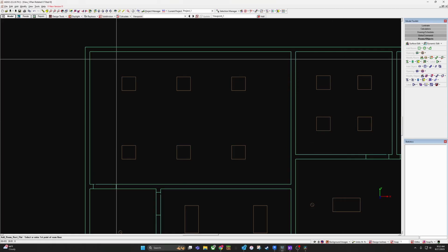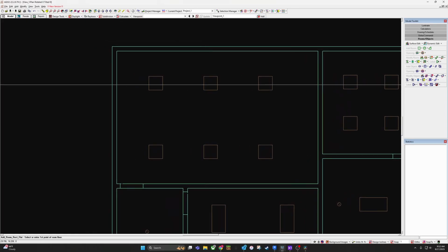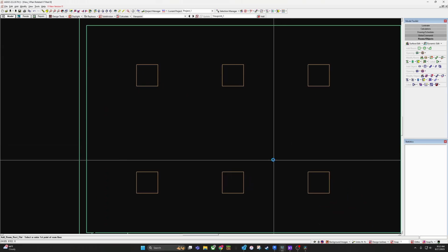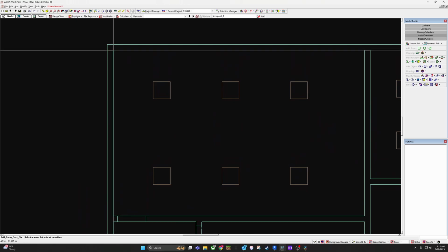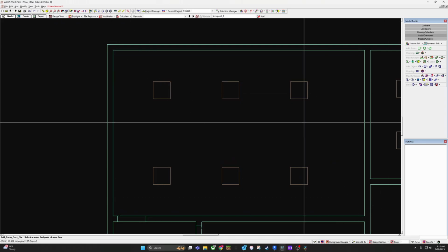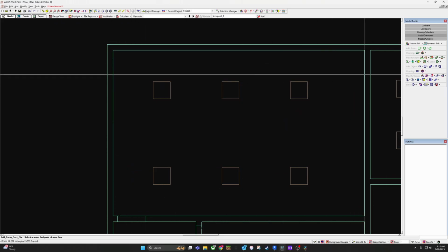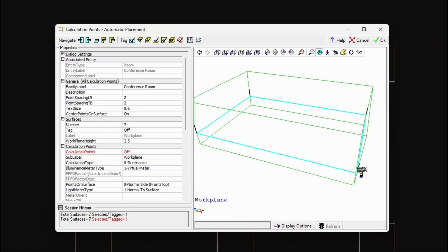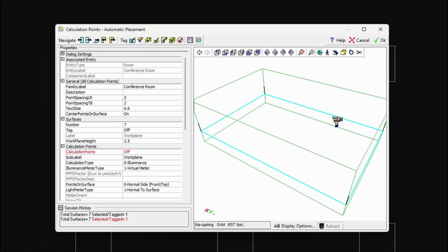9 feet tall. Let's go and create it. So you want to start on the inside corner of your space. You don't want to start in like the middle or out here, because this is where your wall begins. Let's click here. Boom. Right now we can click here, but to make sure that we're doing this precisely, click ortho. Let's go. Boom. Boom. Now just create it in 2 points, because it recognizes that it's a rectangle, so all they need is 2 sides, and then it'll automatically make the other 2 sides.